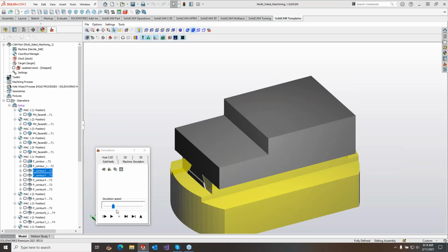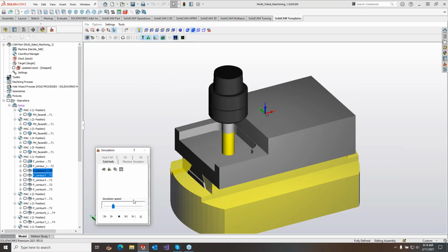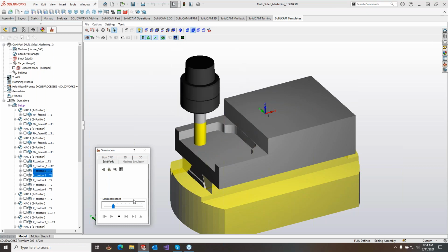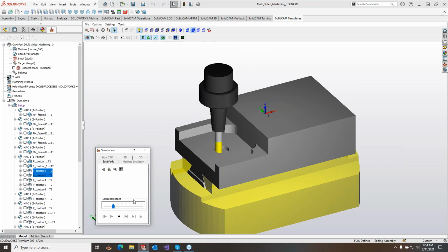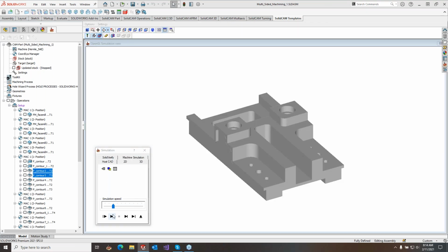If we switch to solid verify, it's a nice, clean, simple environment that just does solid material removal, and we can do stock and target comparisons. The fixture is shown, and there is simple measuring, but there is no wireframe toolpath available here. If we switch to our 3D simulation, it is essentially just a target with a tool and wireframe. This was done generally for 3D and 5-axis toolpath. Things to note here are that fixtures, stock, measurement, and collision detection are not supported in this mode.